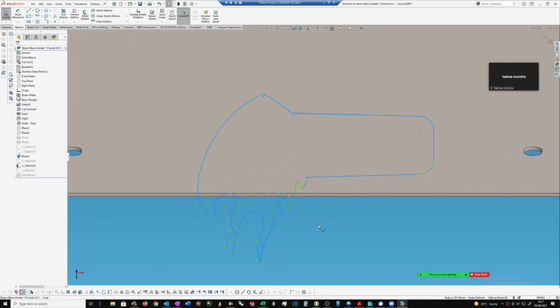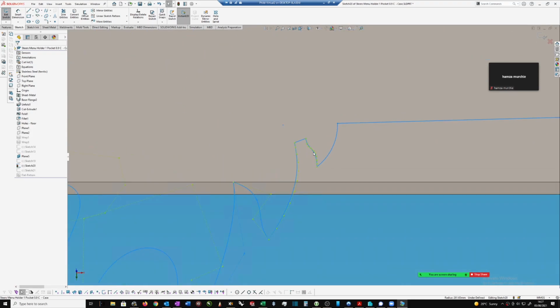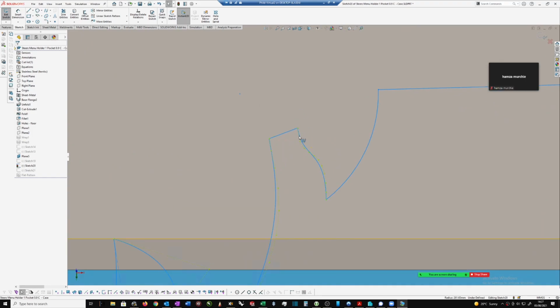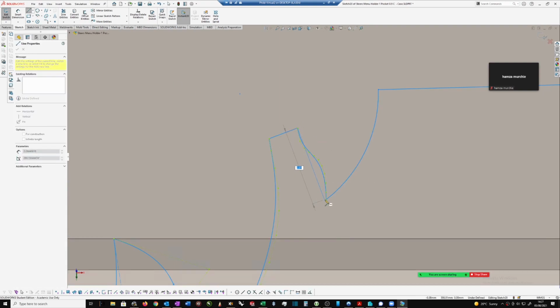See, not going grey. I'm telling you now, from my experience of doing this hours and hours and hours, these lines with the lots of points, these are the problem lines. You have to go and redraw them one by one. So instead of doing that, let's just put some straight lines in here and see if that rectifies it.